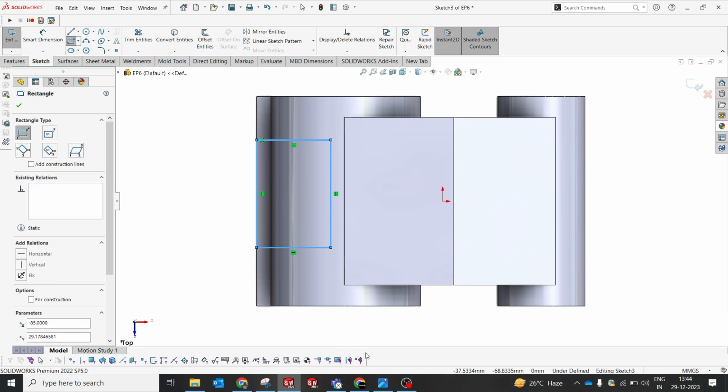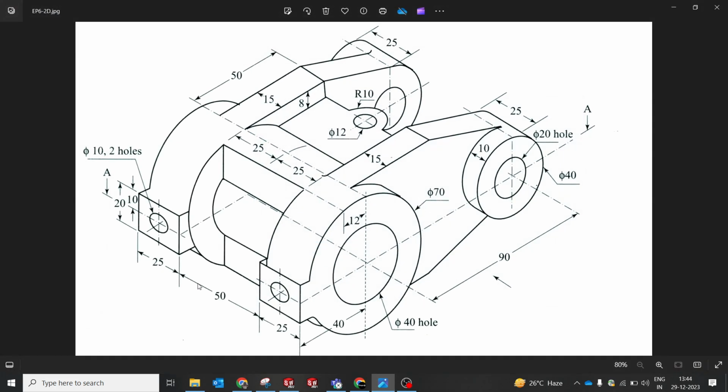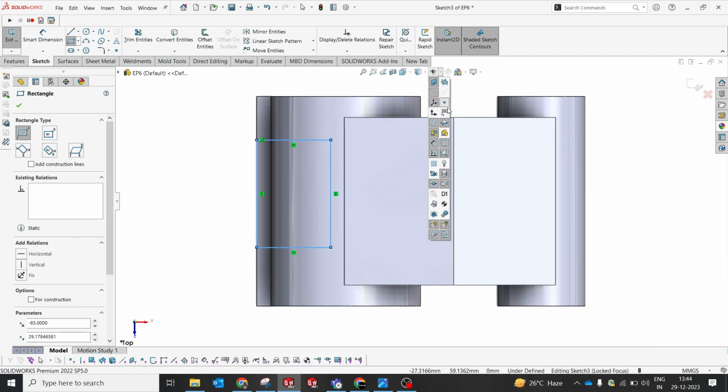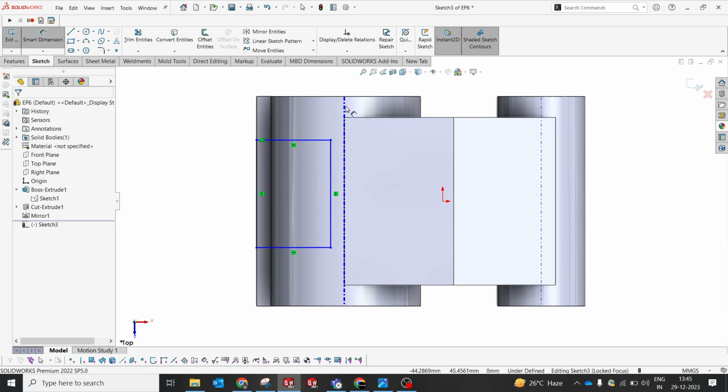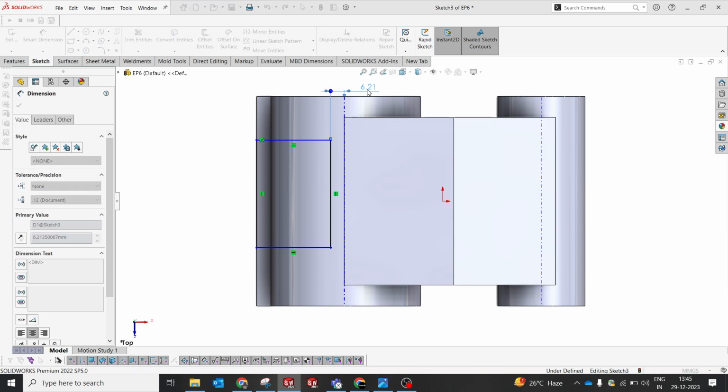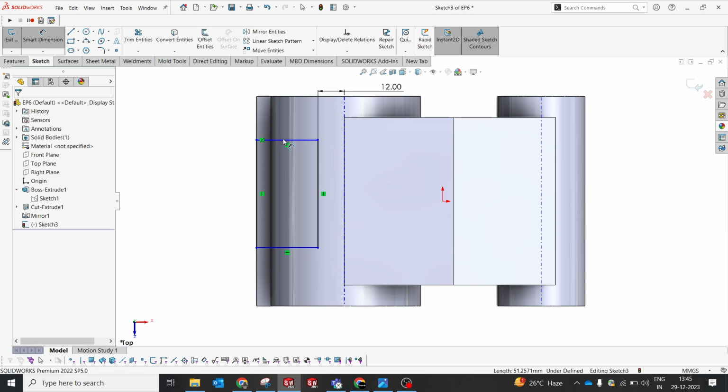Now select OK. Perfect. So again I'm gonna select the top plane, and this time I'm gonna remove some material from this way. So let's try to understand, 25 and 25 each, and here we have 12. Exactly, this is a 12. Yeah, so now we can enable temporary axis, so that we have a reference to take and mark the dimension. So this could be 12, and on each side it is supposed to maintain 25. We'll maintain the same from selecting this edge to this edge,